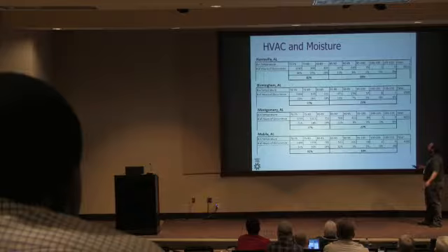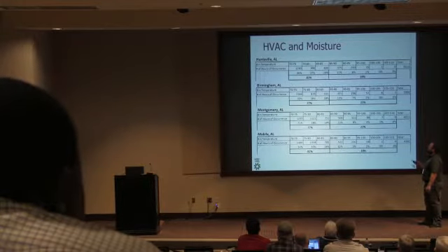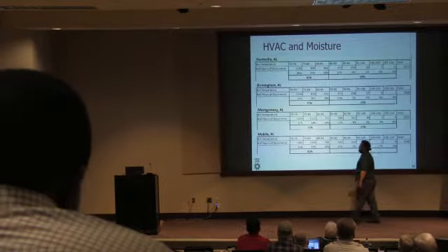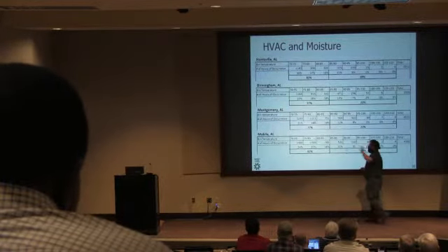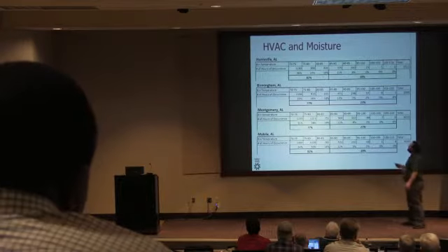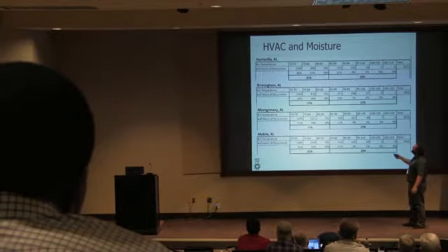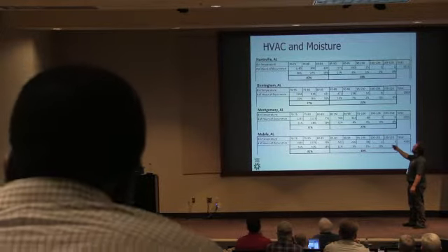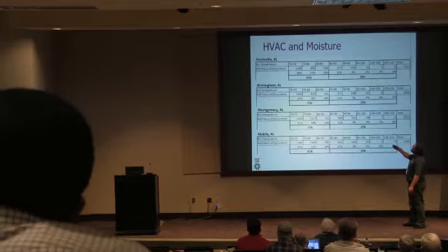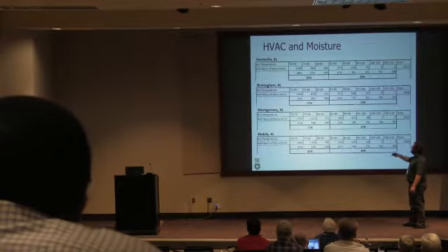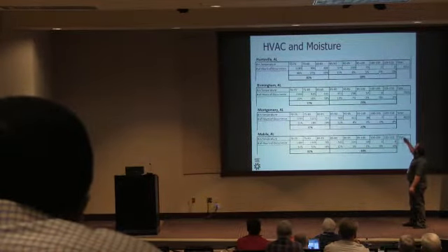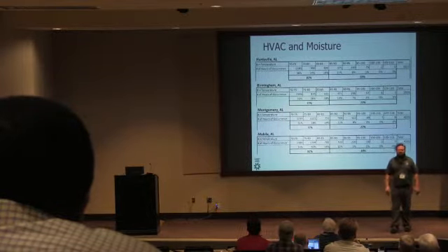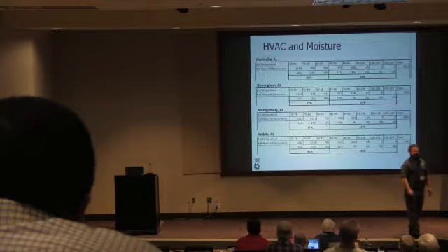This is looking at actual temperatures from a bunch of locations in the southeast, and these happen to be in Alabama, but Birmingham is pretty much Atlanta, Huntsville is pretty much north Georgia, Montgomery is pretty much middle Georgia, Mobile is more coastal, but anyway, you get a general idea of the southeast. You look at observed temperatures, and our ASHRAE design temperatures are somewhere in these ranges right here, where the number of hours of the year that we're above those design temperatures are very minimal, right? So it's not the heat load that makes us uncomfortable in our houses.